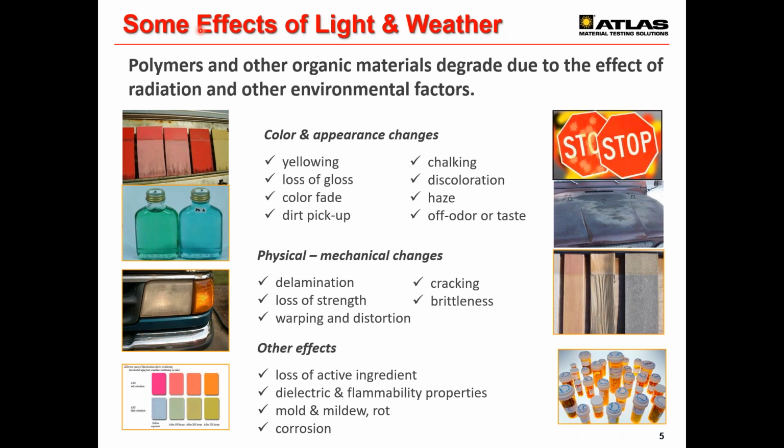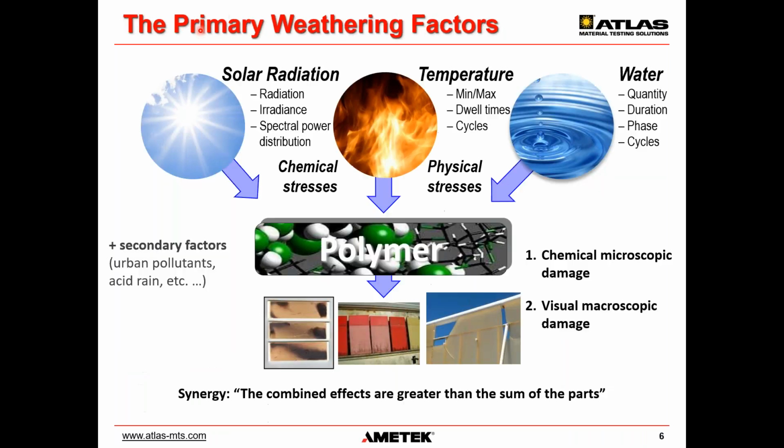And if you test your product for weathering stability, and these are the relevant properties of your product, you have to check those relevant properties after the exposure, after weathering, to see if the product is still good enough for its purpose.